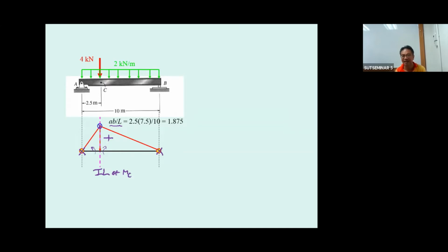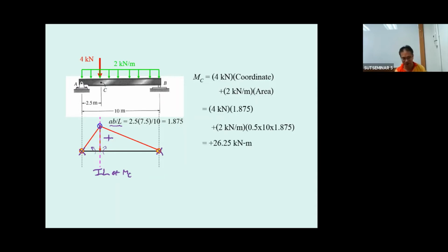You can see the loading pattern is just different depending on whether you determine the shear at C or the moment at C. Then you can determine the maximum moment due to this kind of loading pattern. And then you can use this M sub C and V sub C to design the beam. This beam may be the crane at the F4 building, as I just mentioned before.